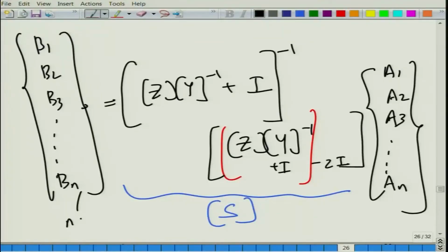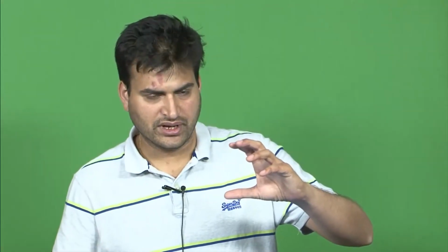So, you can restructure the matrix by putting the first n rows as your n inlets and m as outlets. Of course, conventionally you would analyze a single inlet and single outlet system, but if you look at photographs of a lot of commercial vehicles on the internet, or look at muffler photographs, you will see double outlet mufflers as well.